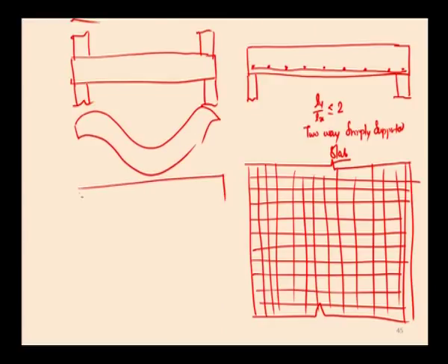In order to resist this deflection over the support, 50% of the reinforcement has to be cranked near the support at a distance 0.1 L from the face of the support and brought to the top. And this is the cranking of reinforcement.